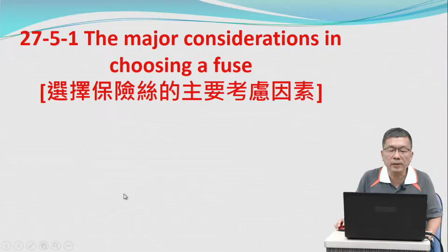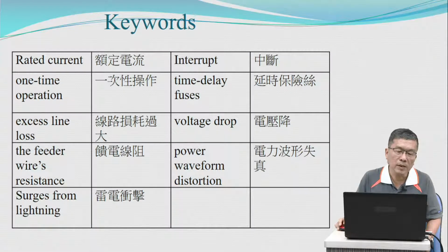The major consideration in choosing a fuse. The keywords: rated current, interrupted, one-time operation, time delay fuses, excess line loss, voltage drop, the feeder wire resistance, power waveform distortion, surge from lightning.